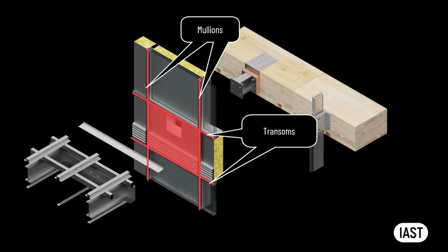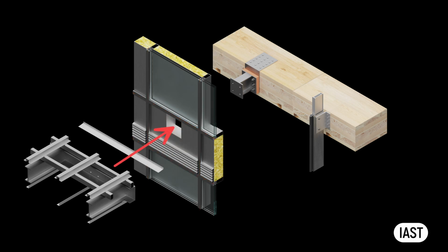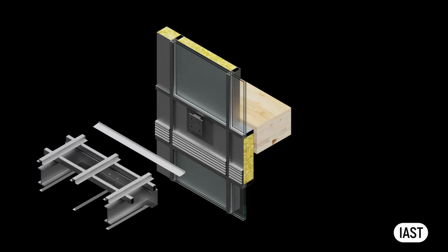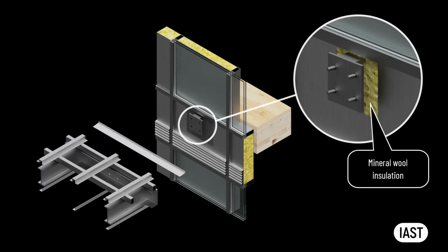An insulated aluminum spandrel panel is installed in place and secured to the profiles with pressure plates. There is a hole in the panel to allow for the balcony stub bracket to protrude through the curtain wall facade. The aperture should be large enough to allow for movement of the primary framework in relation to the facade. The resultant void should be filled with mineral wool insulation.